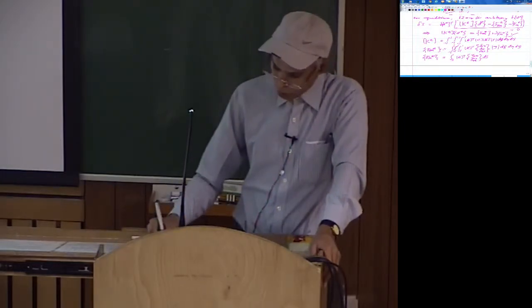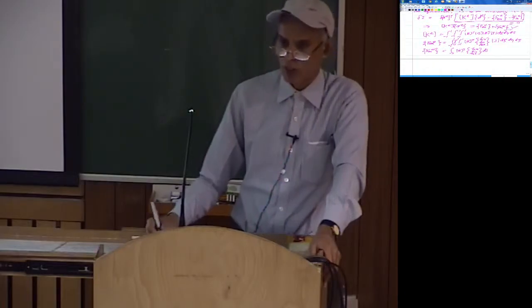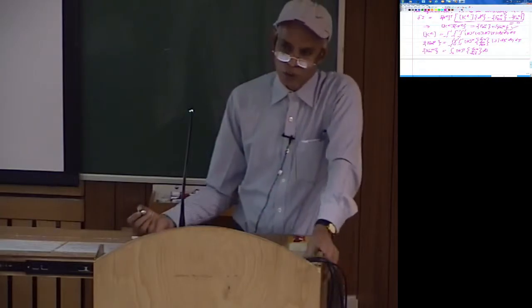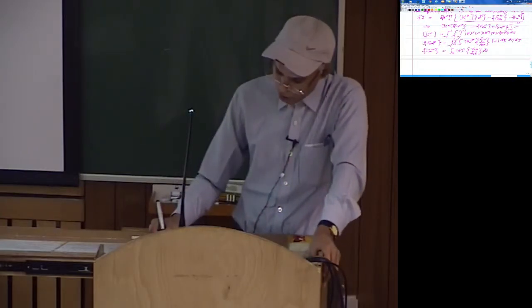So if you want to improve the performance of the element, you can go for a 20 noded element. So then you can have nodes at the center of the faces as well. Then next is of course 27 noded. So similarly, you can improve upon this.